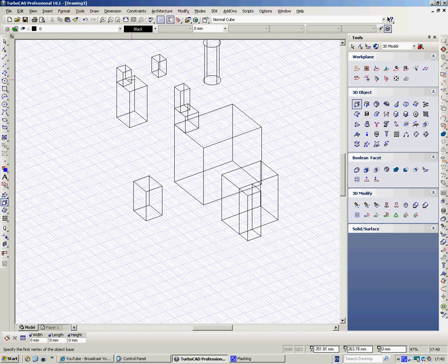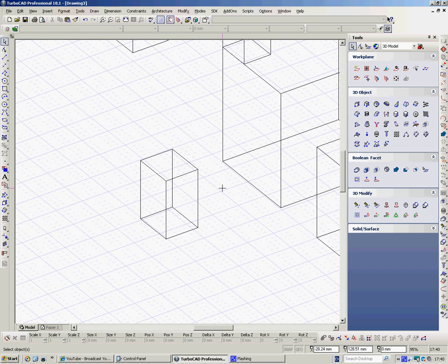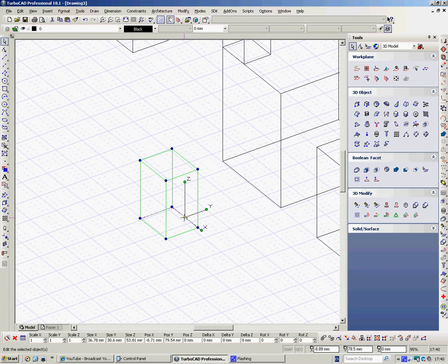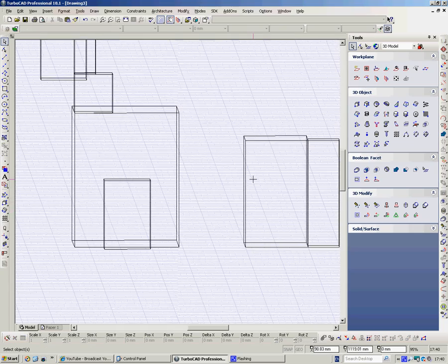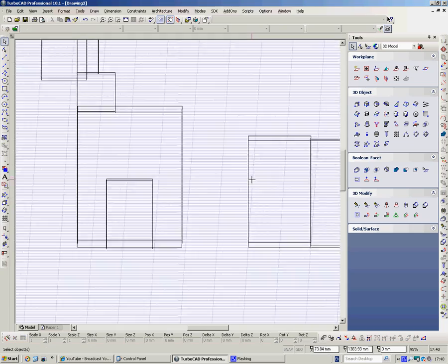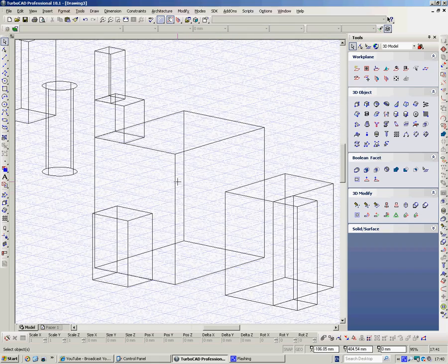It's not up there where these ones were. If I want that box coming out from the center of this box, I've got to use all my usual snaps. I can select that, pick up the origin with a D, snap that, M for midpoint, pick that up, snap that to the center of there, M for midpoint, and then that now is coming out from the middle of that other box. So you have all your usual snaps.